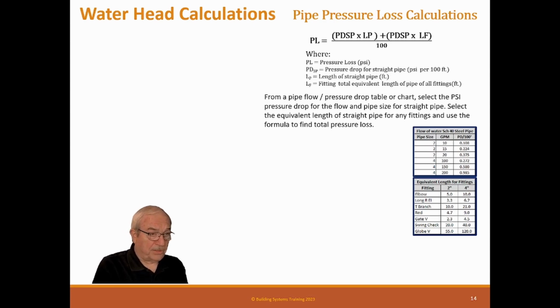Nowadays, of course, they do it with a computer program, but if you make a mistake on this, it's really a problem. You have a big problem. If you're too low, the only way you can change it is by changing the pump, so it's expensive if you mess this up. If you're too big, no big deal. You can trim the impeller and go down, but you can't go up. You can only go down. So this is the process.